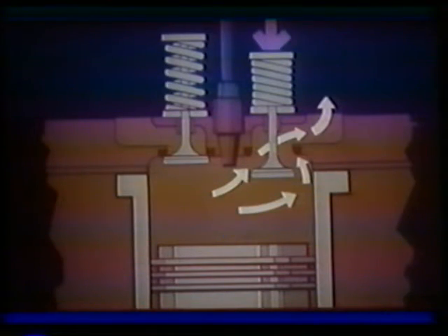On the intake stroke, the camshaft rotates to push the intake valve open, allowing air to pass through a port in the cylinder head into the combustion chamber. Then, on the exhaust stroke, another lobe on the camshaft pushes an exhaust valve open. The piston pushes the exhaust gases out through a port in the cylinder head into the exhaust manifold.